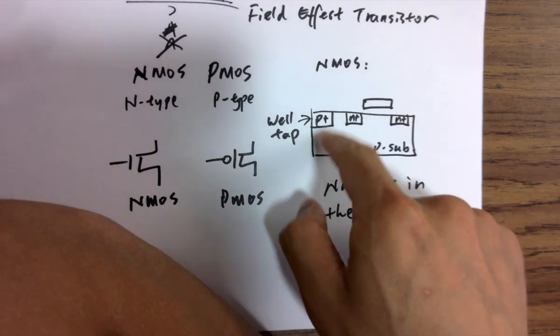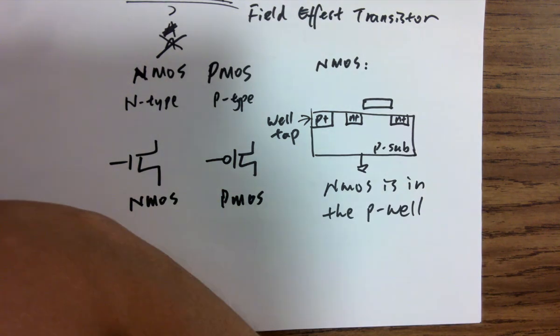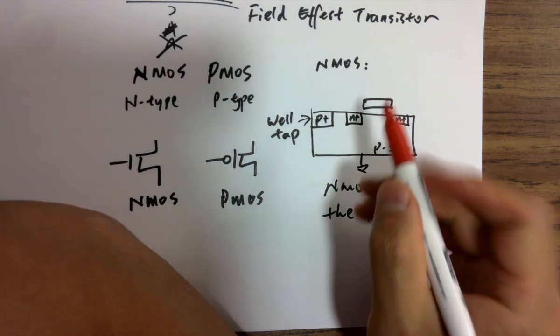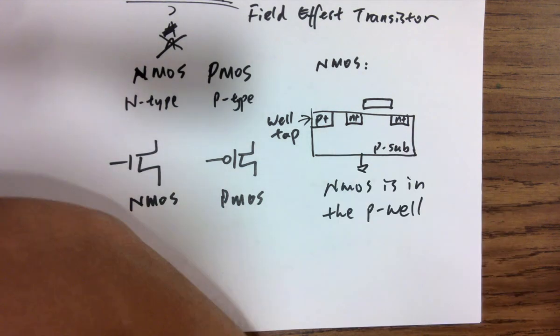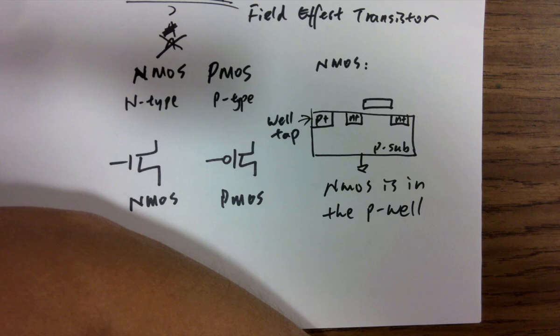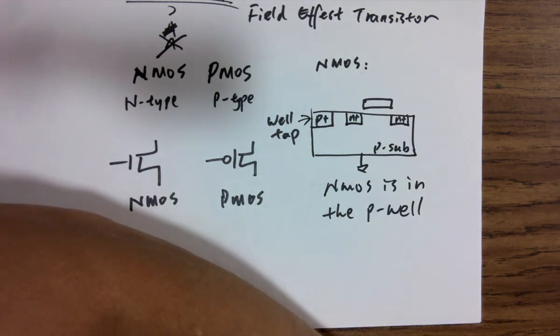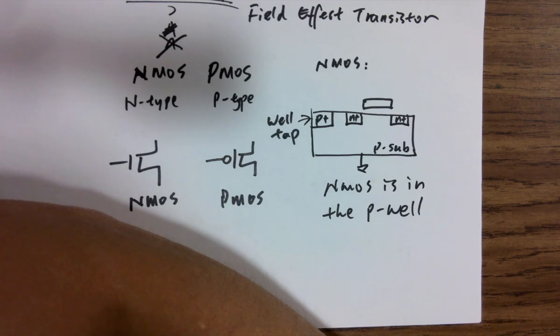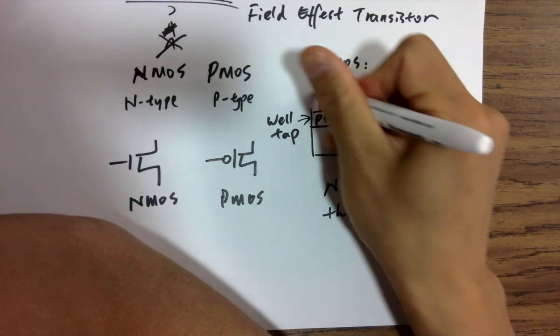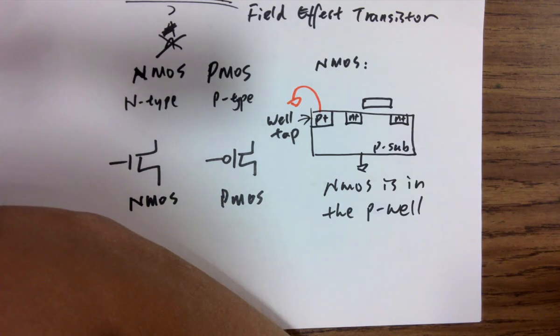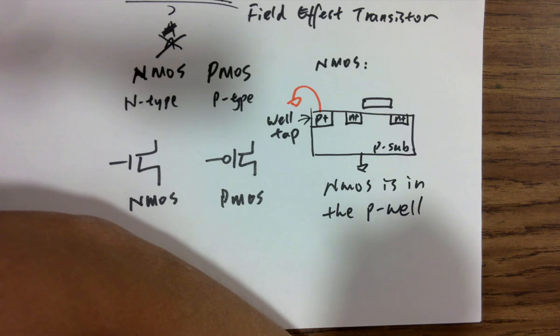But now, why do we need a P-type tap? Come back to this topic. P-tap means it's like tapping, right? The wafer is a P-type material, and P plus is just a more heavily doped P. The sub is also P, but it's lightly doped, so it's less conductive. But the P plus is heavily doped P, so it's more conductive. This is eventually shorted to ground, and that's how we short the P sub to ground.